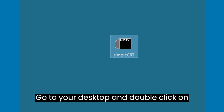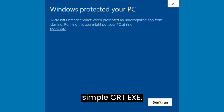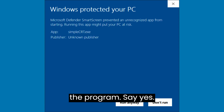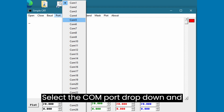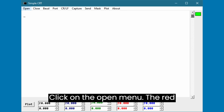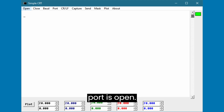Go to your desktop and double-click on SimpleCRT.exe. Windows may ask if you really want to run the program. Say yes. Select the COM port drop-down and select the COM port for your Pico. Click on the Open menu. The red box should turn green, indicating that the port is open.